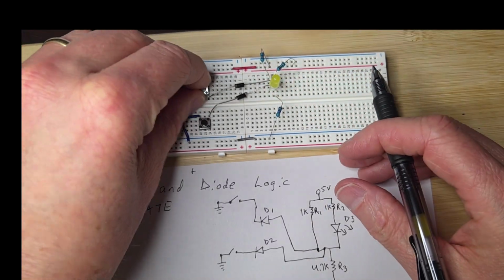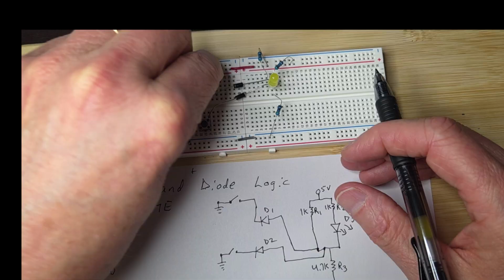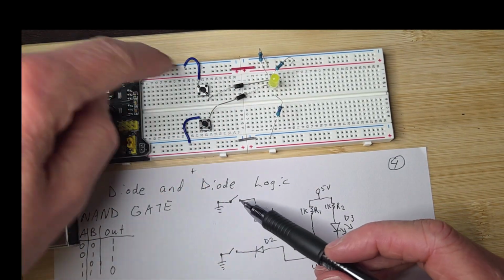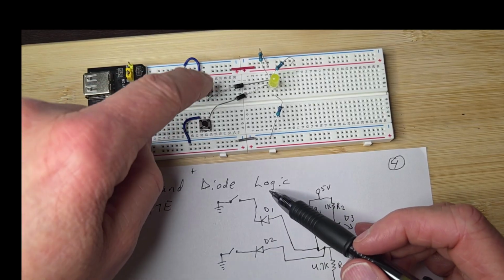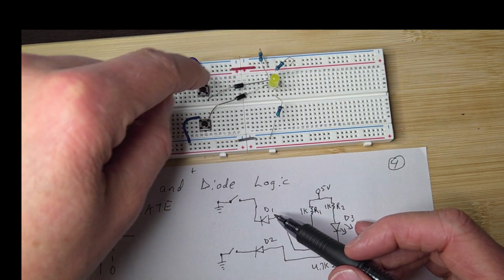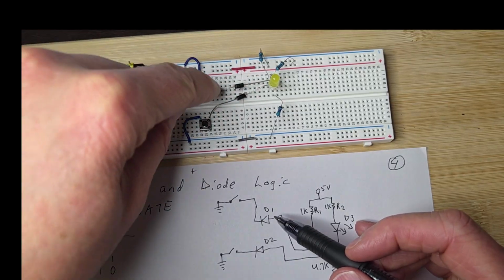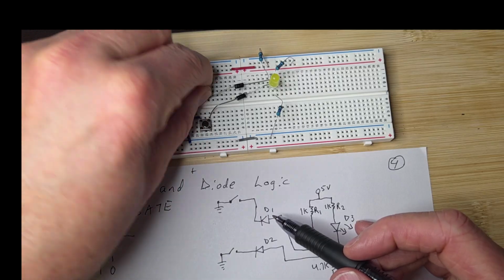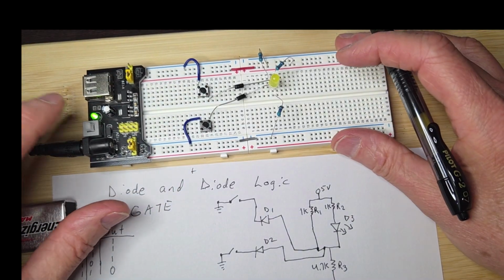But there's my switch, it popped loose. So I have these diodes switching over to ground with the switch. You can see the switch here, and this is the cathode going to ground. So that when I turn it on, the diode's going to be forward biased. Same way with this one. So this is A and B. And so let's power this up.